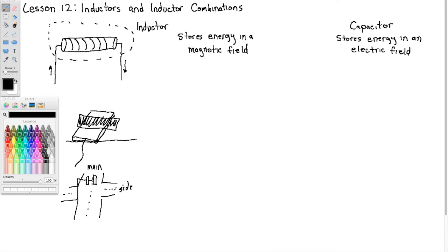Sometimes motorcycles do not have enough metal to be sensed. So the resolution there is you'll see riders putting big magnets on their motorcycles, and that will be sensed then in this magnetic field of the inductor.